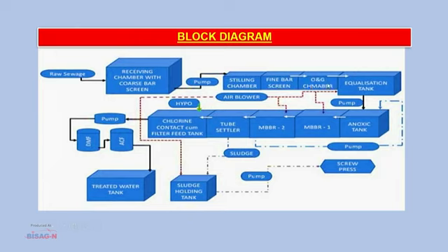Then the sewage goes from oil and grease removal to the equalization tank. The sewage is generated in an erratic pattern throughout the day. In the morning and evening it is higher than average, and at noon it is lower and even zero discharge. Also in late night. To equalize the irregular flow of sewage, a collection tank is provided so that the average flow can be pumped to the process reactors to achieve desired results round the clock.